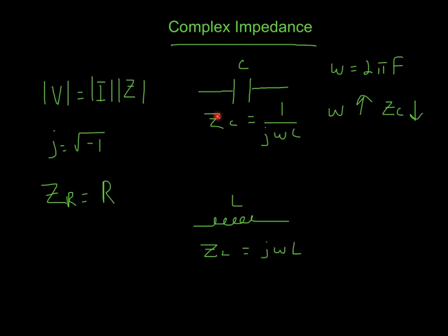Let's take a look at that. If you remember from last screencast when we talked about a capacitor, the picture is great. It's a block. You have a wire coming here, there's the plate, and there's nothing connecting it in between. So if omega equals 0, let's look down here, this thing is infinite, an open circuit. Perfect. So what happens in the other extreme when omega is very high? When omega is infinity, this thing looks like a wire.